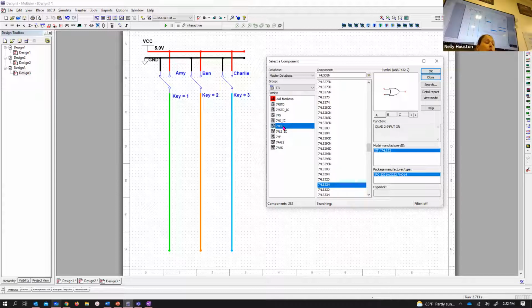Now, what part numbers? Remember I told you it was 7408 for the AND, 7432 for the OR, and 7404 for the inverter. Now, if you look here in the center, there is 04, because these are LS family, that's the devices we're using. There's an 04N and an 04D. You want the letter N because those are the ones that fit on a breadboard. The D, the package is different, okay? So always select the one that ends with the letter N and only use chips from the 74LS family. That's never gonna change all year long.